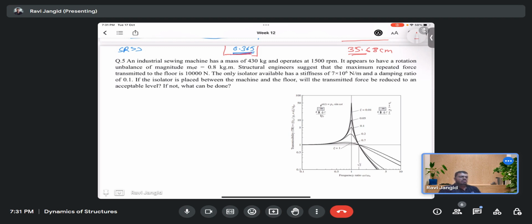That's all. If your structure is flexible, like in the previous question we discussed, we found there is not much difference with the base isolator, around 5 to 6% reduction in the base shear. So what does that mean? If I use it at huge cost and get only 5 to 6% reduction, that doesn't mean much for me. Did you get it?